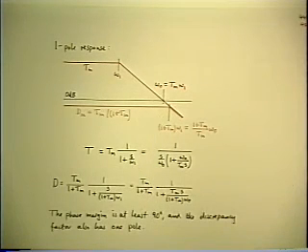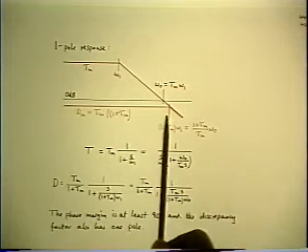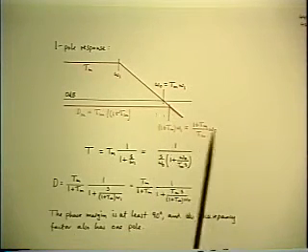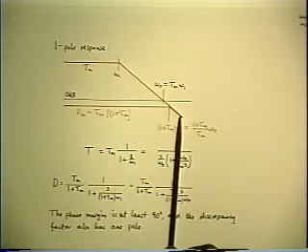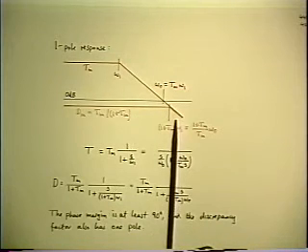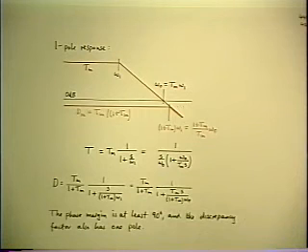Now that's the ideal case. That's the best possible shape for D that you can ever get, given that it's going to roll off somewhere. So flat up to a certain frequency and then a smooth 3 dB corner is the best you can do. In other words, it's the most graceful roll-off of the closed loop gain you can get, where it begins to deviate from the G infinity. What's the phase margin in this case?